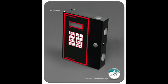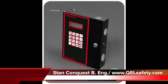I'll just talk a little bit about the controllers. The M controller, as Barry mentioned, has 32 digital or RS-485 channels and 8 analog inputs. Those analog inputs can be from any type of device. So if you have a temperature sensor or humidity sensor, as long as it has 4 to 20 or 2 to 10, it will be able to display that value.